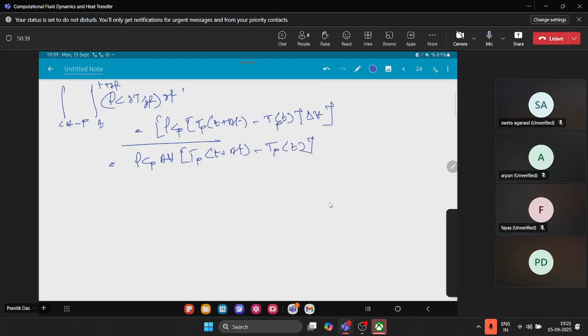This is basically my P control volume, and the spatial discretization we will do on the right hand side of the equation. For the right hand side, the first term is the integral from t to t plus delta t of k A dT/dx at e minus k A dT/dx at small w, multiplied by dt', since I have converted that volume integral into an area integral.